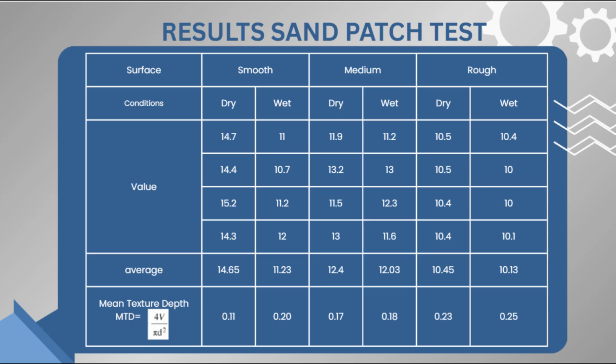These are the results for the sand patch test, where at the end we calculate the mean texture depth, the MTD, by using the formula 4V over pi d squared.